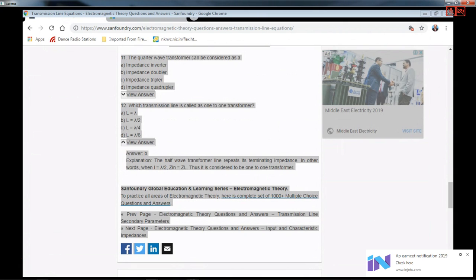So the ratio must be equal to -π. So θΓ − 2βz' is equal to −π, or θΓ is equal to 2βzm' − π. That zm indicates the distance to the first minimum. So by measuring this distance zm' and knowing β, you can estimate θΓ.